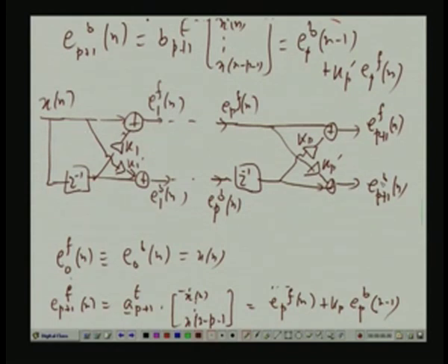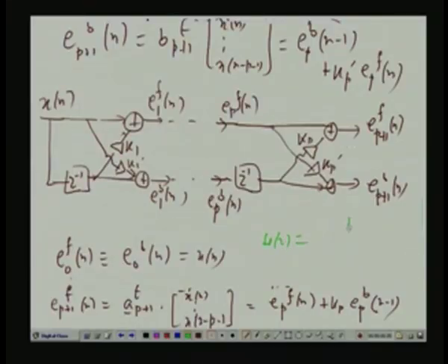Okay. So, it just shows how the AR modeling problem is related with linear prediction and lattice filters and all that. Only thing that I have so far not shown, and I should show in maybe 5 or 10 minutes in the next class, is that when you solve the Yule-Walker equations, you get a set of coefficients AP1, AP2, dot dot APP. You put them back in the transfer function for A z. So, you get a transfer function something like this, A z dash. This is that AR model transfer function.